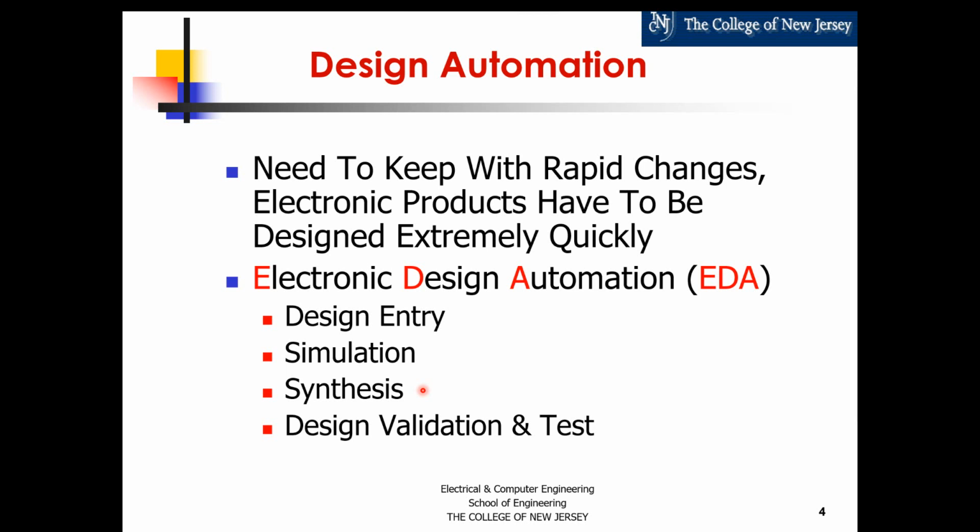The other part is that if you're going to be giving this synthesis tool the directive of what to do in the way of the description of the hardware via a hardware description language like Verilog, you want to know if you did it right, if your description matches what you meant to describe. So you need to simulate it. You need to test it. That's the other part of the infrastructure. All of that is in Vivado: your design entry, your simulation, your synthesis.